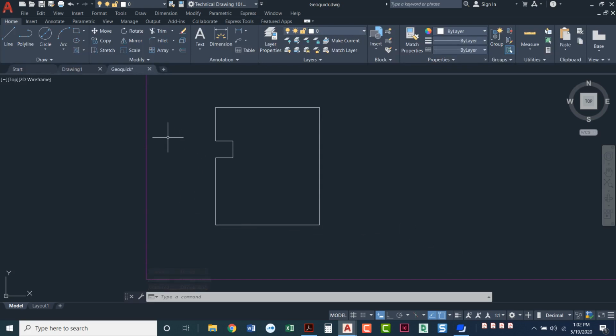All right, so what it's asking me to do is start the circle command. By default, the circle command that you will see up here is a circle radius. But whenever we have circles, we're given the diameter. We never give a radius for a circle. So this will catch you, and I just want to show you. I'm going to show it off to the side here.